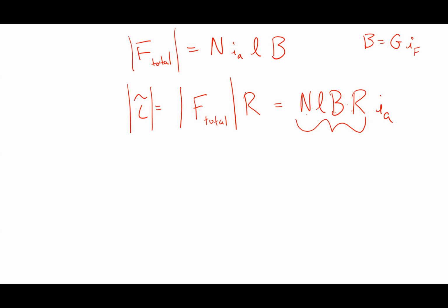Important thing that I got here is I said, again, if I see you on the street in 10 years and I try to figure out what I taught you, if anything, this is one of the two things that I would expect you to remember. Not that formula, but it's to say that torque is proportional to what? Current. Torque is proportional to current. And that's true in all the motors we've seen. If I want more torque, I need more current.